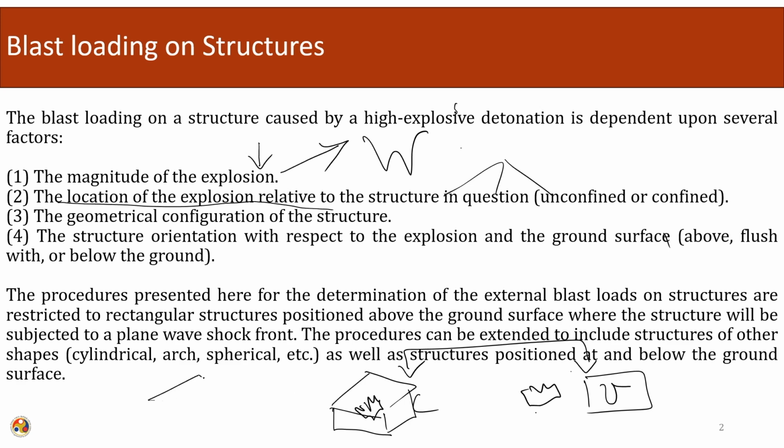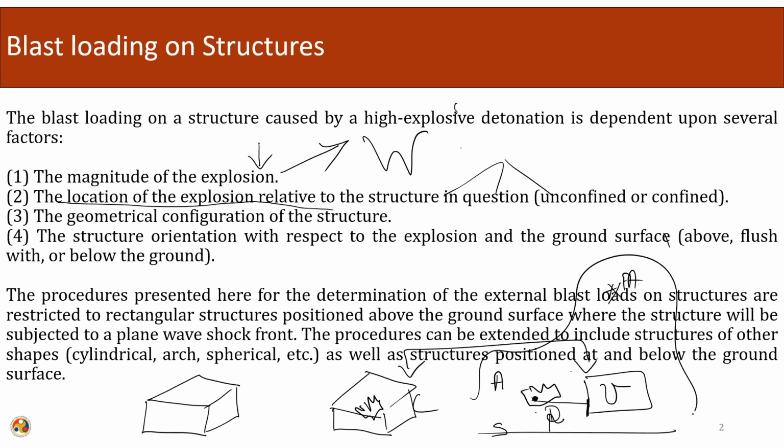If we go deeper into this confined and unconfined issue, we will see that in an unconfined blast, the distance between the blast and the structure, that is the standoff distance, plus the location of the blast relative to the structure, whether it is a free air blast, an air blast, or a surface blast, will again be a function of the relative location of the two. So depending upon these factors, the amplification in the pressure wave will occur.